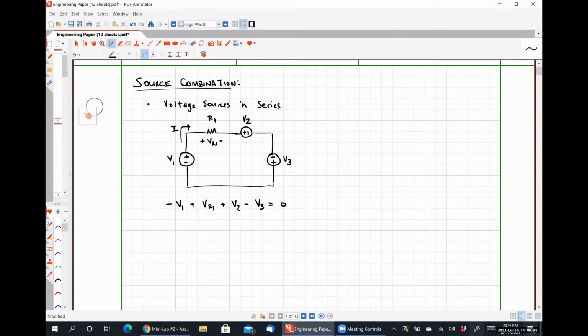So before we move on here, does everybody agree with the signs on the 4 different components of this equation? Yeah, so what I did is I started at this bottom left-hand corner, and whenever I see the negative polarity terminal first, it gets a negative sign. If I see the positive polarity terminal first, as I follow the current around this loop, I use the positive sign. So that's why everything has the sign it has.